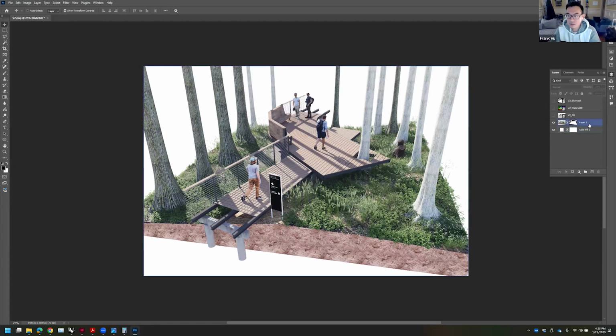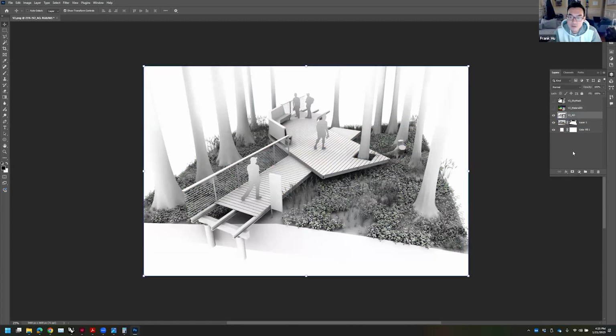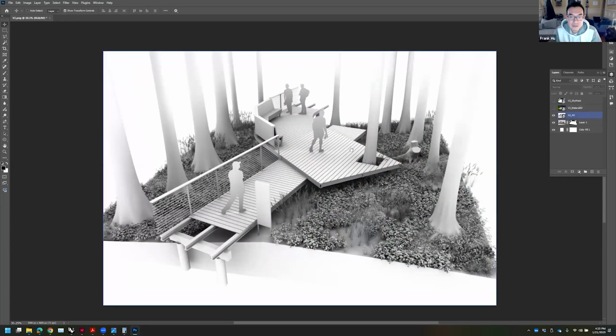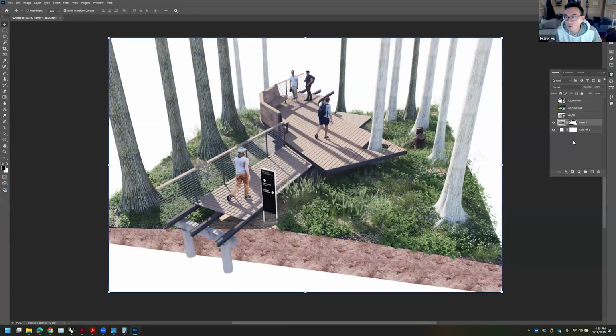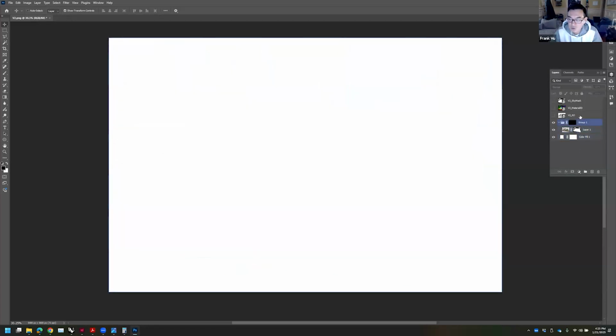And then I think this is a technique you can try, which is to use this AO layer here as a way to remove detail in areas that you don't want us to focus on. So what I will do is I will take this base render here. I'm going to hit Control G to group it, and then put a mask on top of that group. And then I'm going to take that mask and invert it, so just Control I to invert it.